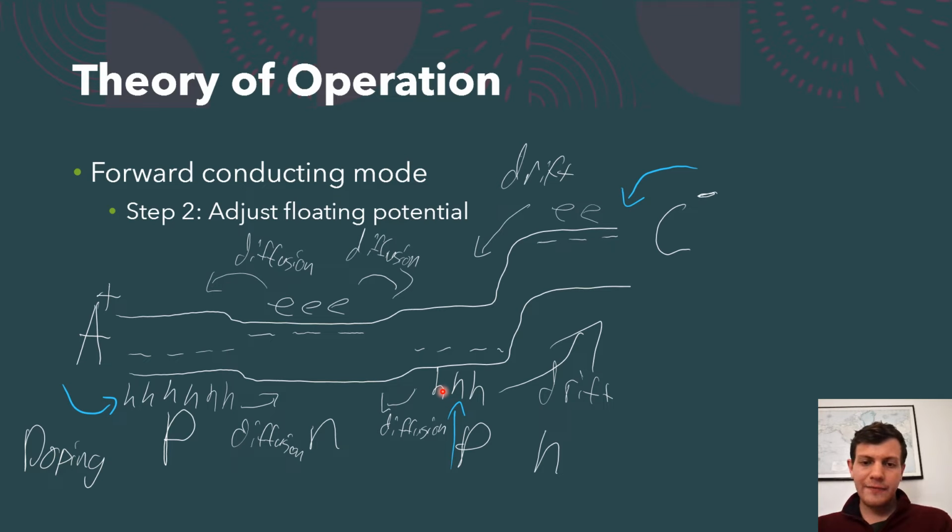The main source of current here is this drift current, as electrons kind of tumble over this potential, and holes tumble up that potential, or down the potential for them. Everything's downhill with drift current, but they're going to be annihilated as soon as they get there. But we're going to see some rebiasing of these regions.